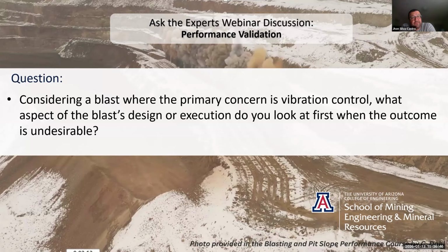There are many things that you can start to check here. From the design, I will check the timing. Timing between explosive charges, to see if ideally you are doing the waveform superposition to mitigate the vibration limits.